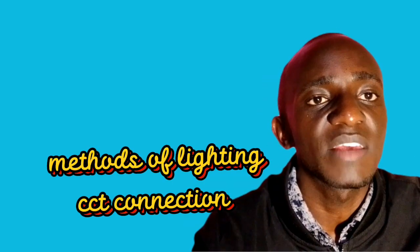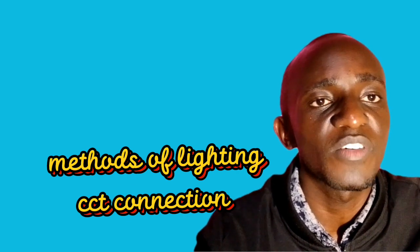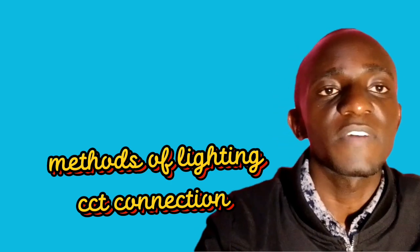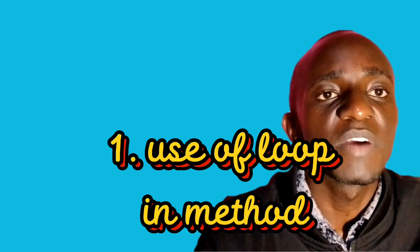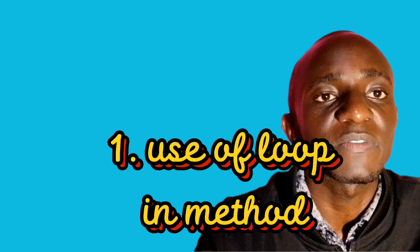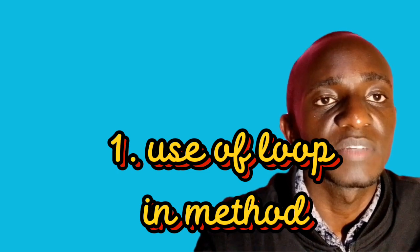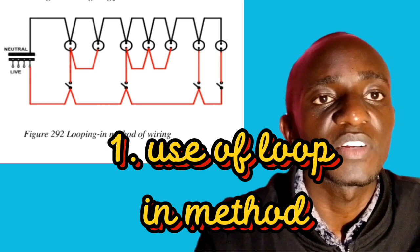So we have the 3 most commonly used ways of connecting a lighting circuit. The first way is by use of what we call the looping method. The looping method is where the common of the first switch, or the supply part of the first switch, supplies the second lamp, becomes the supply of the second lamp. That's what you call a looping method.